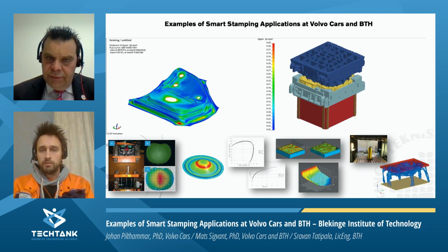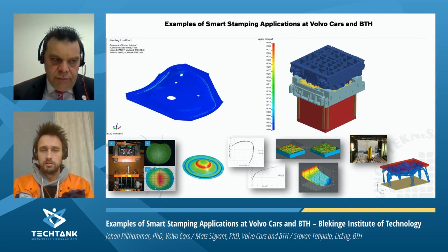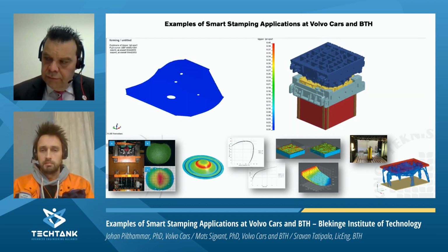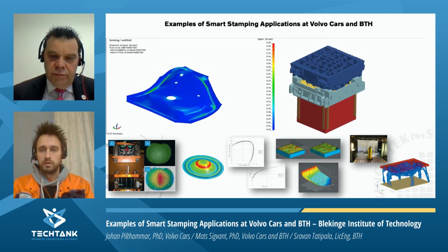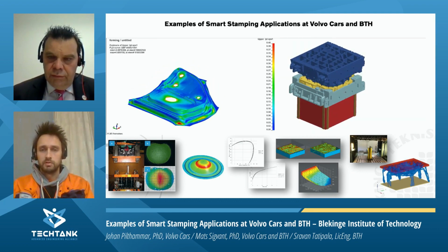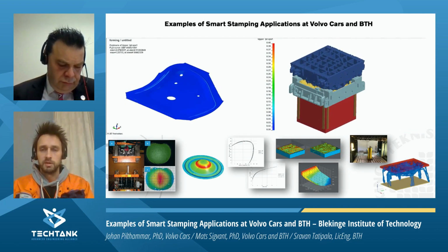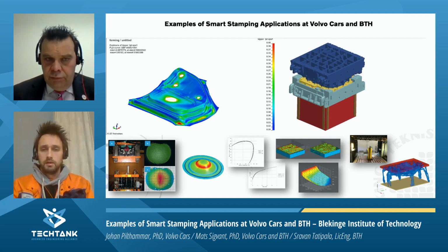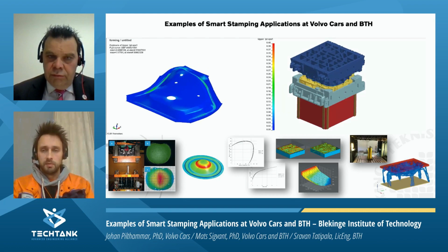So if we have the measured press lines, the die structure, and the forming surfaces, then meshing, setting up the model, and running it can be done in less than a working day. So a full virtual tryout of, say, the blank holder or punch or matrix can be done in a few hours. So the different parts of the simulation model, we are quite happy with that right now.